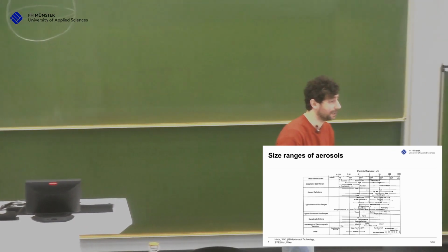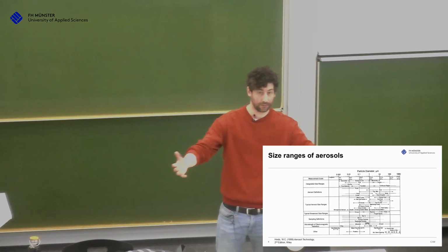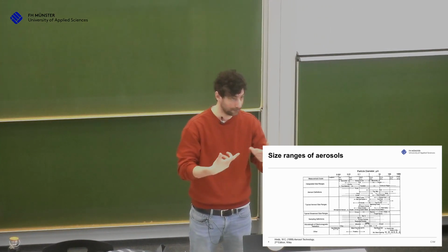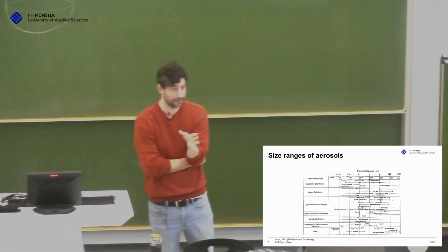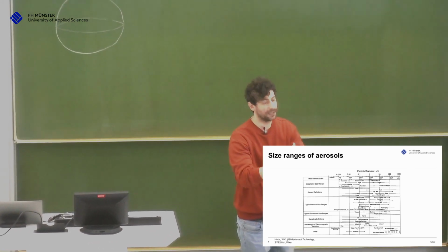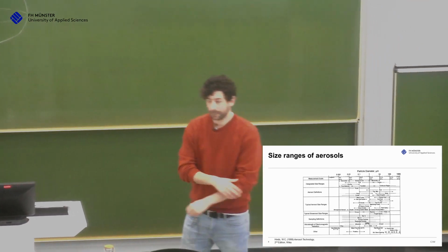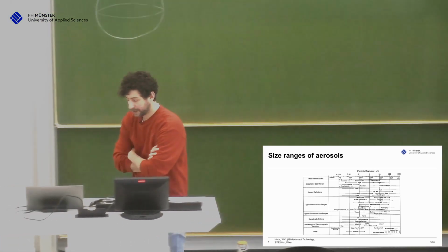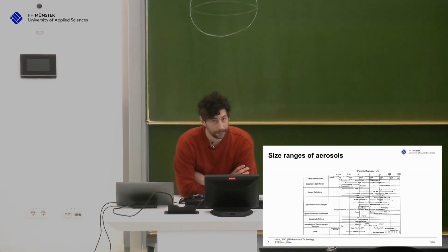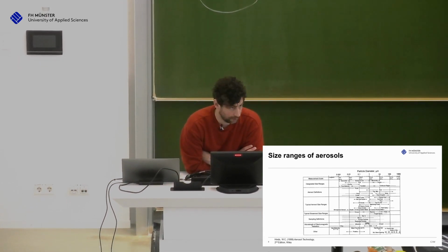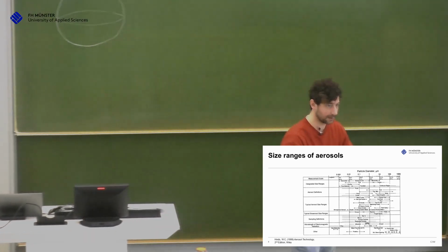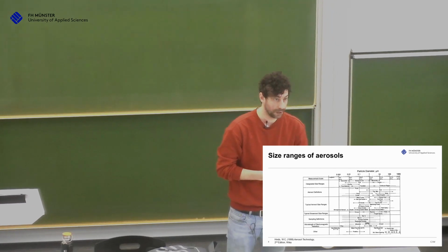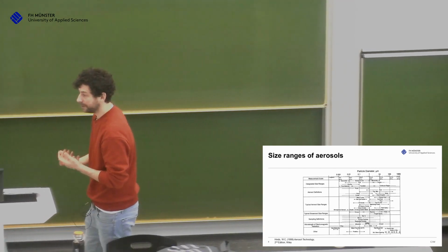So the whole medium. So basically, continuum means you have a fluid. So normally, continuum is for fluid mechanics, okay? And you have a fluid, and the fluid has homogeneous properties. The density, I mean, there could be a temperature distribution, whatever, but these things are continuous. And you don't describe a fluid by molecules. You don't care about molecules. You just say, okay, water has homogeneous properties, that's it. You don't think about water molecules. And this makes calculations very, very easy.